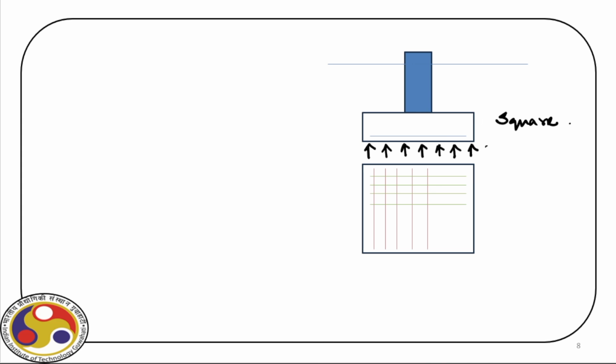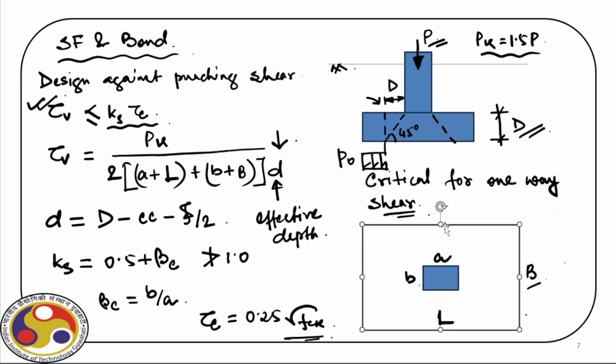Now, these are the rebars in one direction, and then we'll have other rebars in the orthogonal direction over the entire length, right? Now, why do I bring up this issue? Because for a square isolated footing, these rebars continue in this direction. So these rebars are uniformly placed. So that point is to be noted. Now, when we have a rectangular footing, this arrangement is slightly changed.